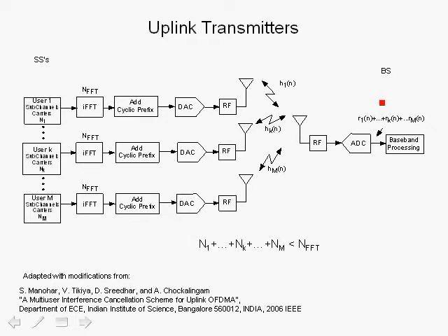So going back, for example, if user K happens to be further away from the base station than user 1, then user K transmits first or earlier than user 1. Then user 1 transmits. Hopefully they both arrive at the same time at the base station. And as we discussed previously, they have to arrive within at least a window of 25% of the cyclic prefix or guard interval. Due to the nature of the inverse FFT, the data is cyclic in an FFT, and we can actually recover the symbols within that 25% of the guard interval with no problem.